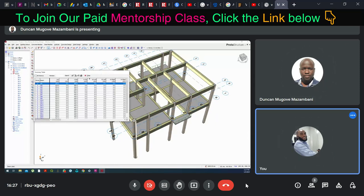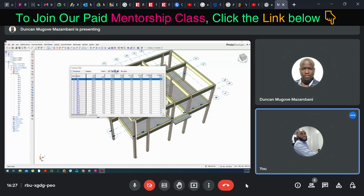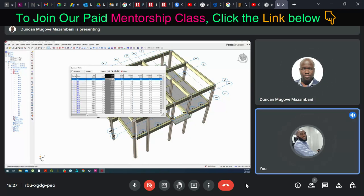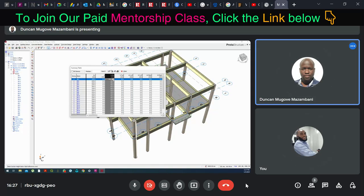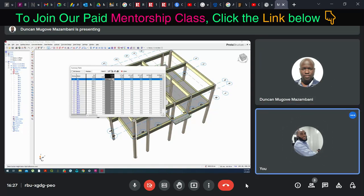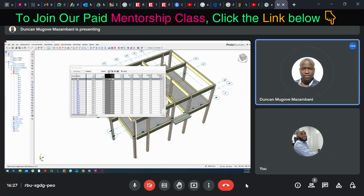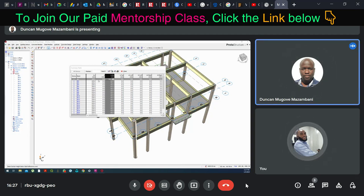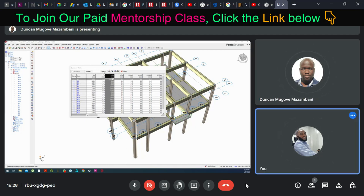Now you can see where you have the 450 H beam. Click on that. Now you will see something like a pencil with a paper, that's the column-wise. Click there. Now type your new depth as 300. Have you clicked there? Click that place. It should show you a dialog box.